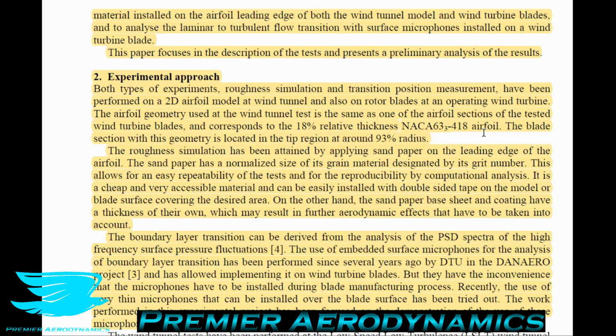So when you start sanding your object, you sand for, let's say, half an hour and it gets smoother, then you sand for another 5 minutes and it's not getting smoother anymore, then you can say that, okay, this roughness corresponds to the surface roughness given by the sandpaper. Now you can quantify what the surface roughness of your object is. So sandpaper is very useful, and we should use it as much as possible as an easy way to determine and control our surface roughness.